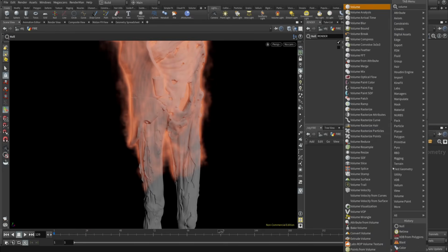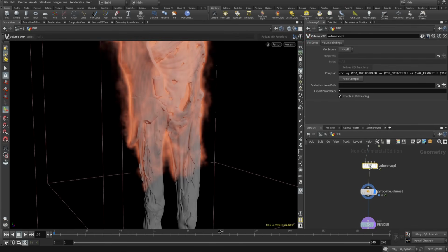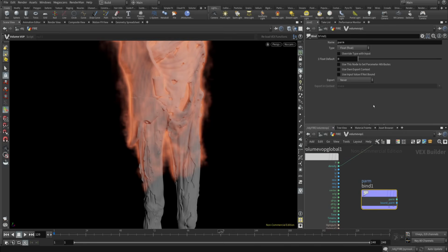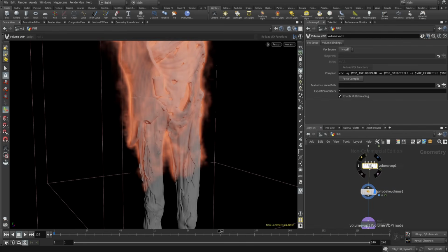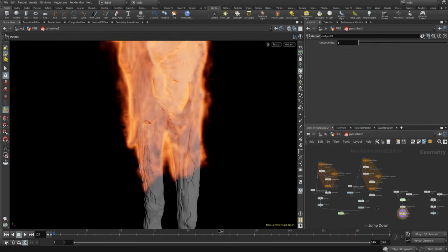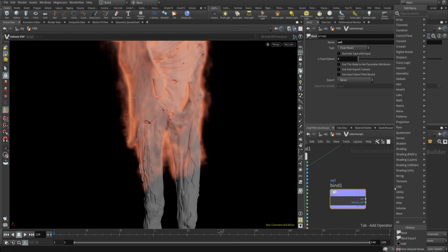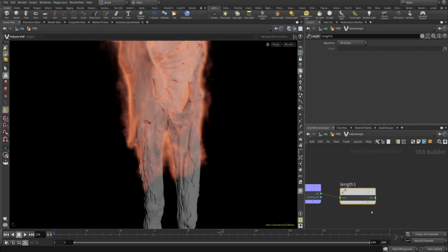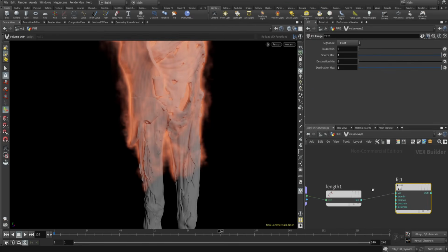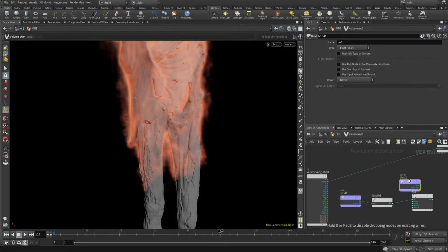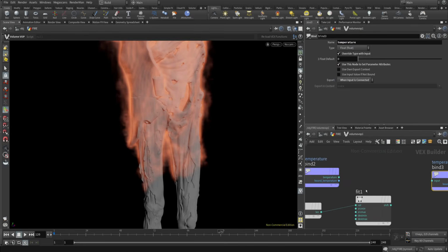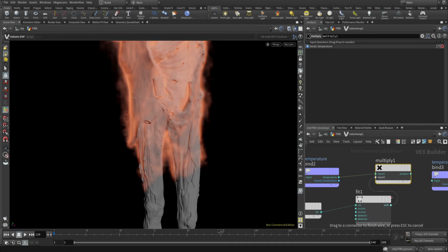Here you need to drop down a volume VOP, and inside it we need to compute the speed of the velocity field, or the length of the velocity field. Bind, I want to read vel. Do we have any velocity? Yes, it's already done. And here the type should be vector. I'm going to compute the length of the velocity field. So here we have speed. Use a fit range to control the output range values, and we need to read temperature. The type is float, temperature, and bind export to export our new temperature field, and multiply first input, second input, and output.